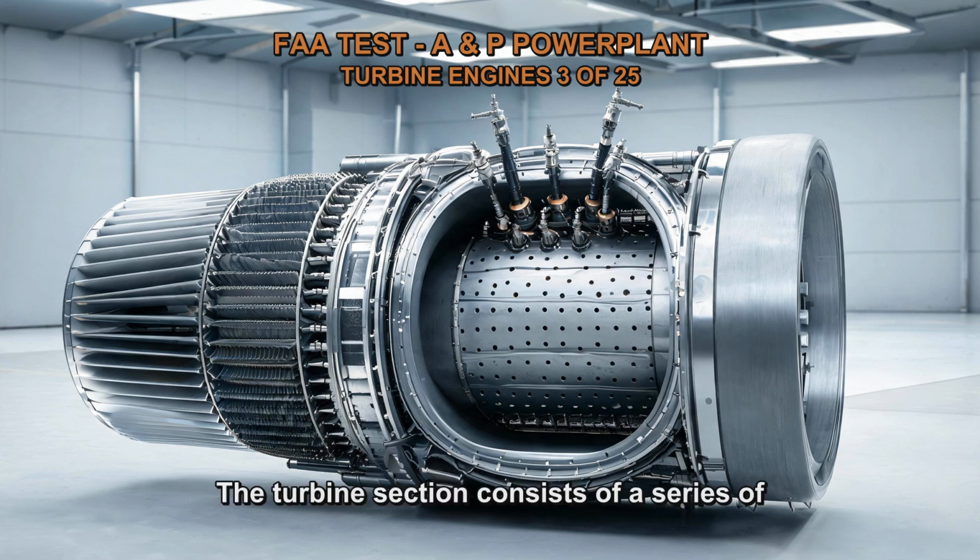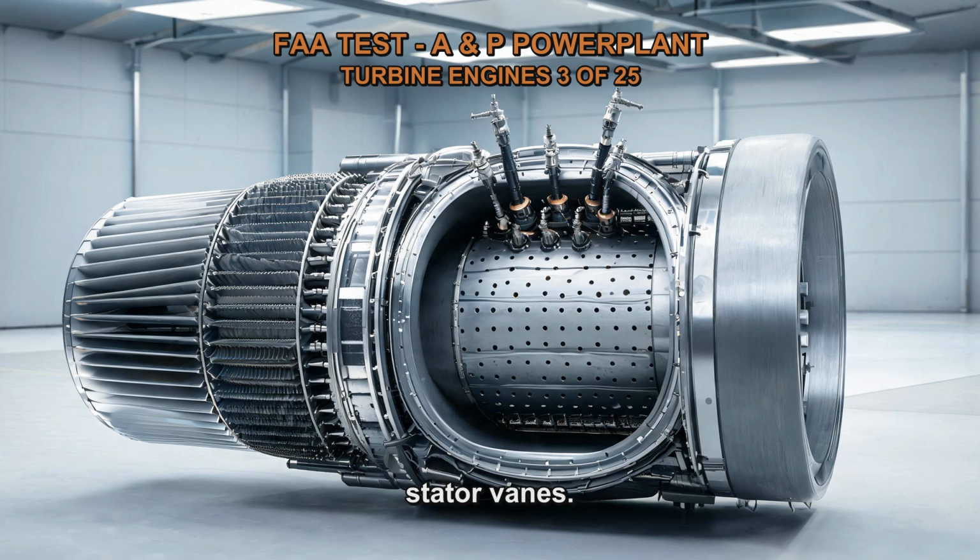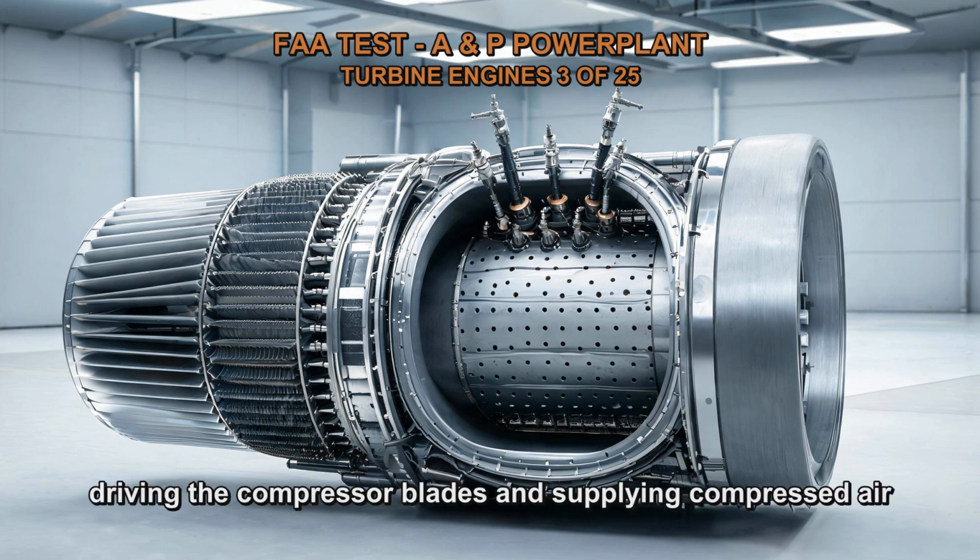The turbine section consists of a series of turbine stages, each comprising a rotor and stationary stator vanes. As the hot gases flow over the turbine blades, they expand and transfer their energy to the turbine rotor, causing it to rotate. The rotational motion of the turbine rotor is transmitted to the compressor section via a shaft, driving the compressor blades and supplying compressed air for combustion.